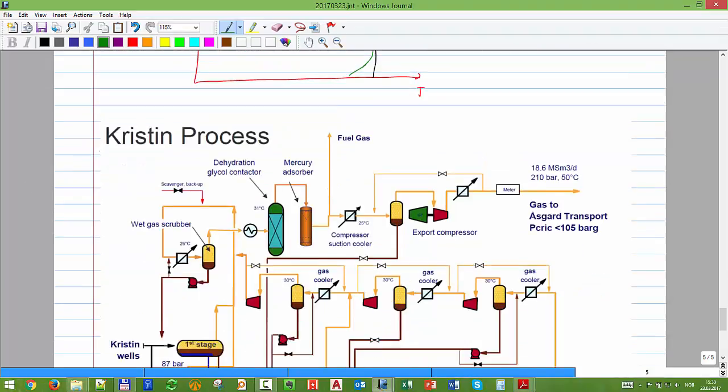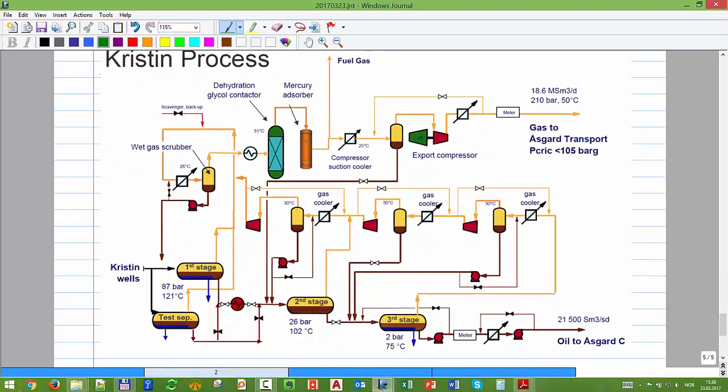So you see that the same thing is happening for every stage. If we go now to the second stage, again I'm taking the gas out, I'm cooling it, I'm using a scrubber, I'm using the pump to send the liquid through the inlet of the second separator, and then I'm compressing it to take it to the same line. In this case, all of the streams go again through the scrubber of the first stage. Okay, and also for the second one exactly the same.